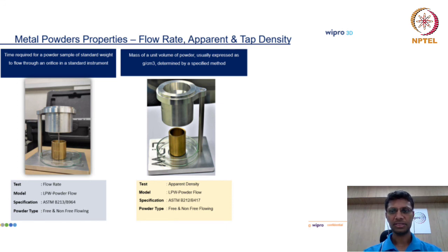Apparent density is influenced by powder shape, size and size distribution. If a powder sample results in a lower apparent density, lower than the previous sample of the same material, it may suggest that the particle spacing has increased. Apparent density is calculated by weighing the mass of powder required to fill the volume of the calibrated apparent density cup.